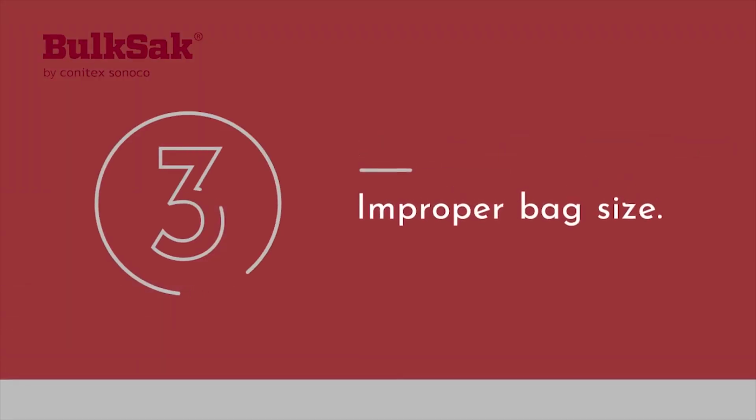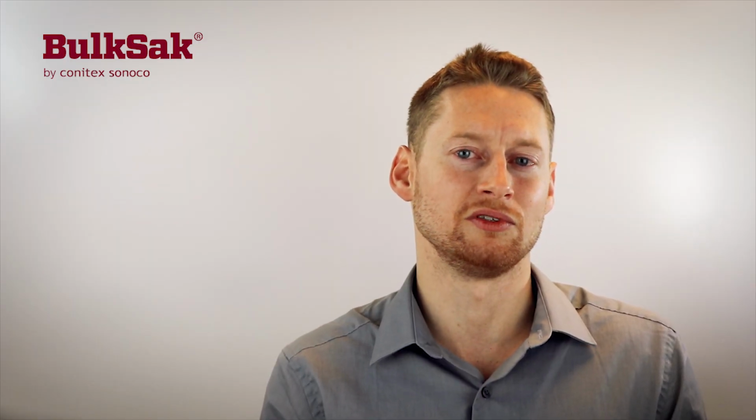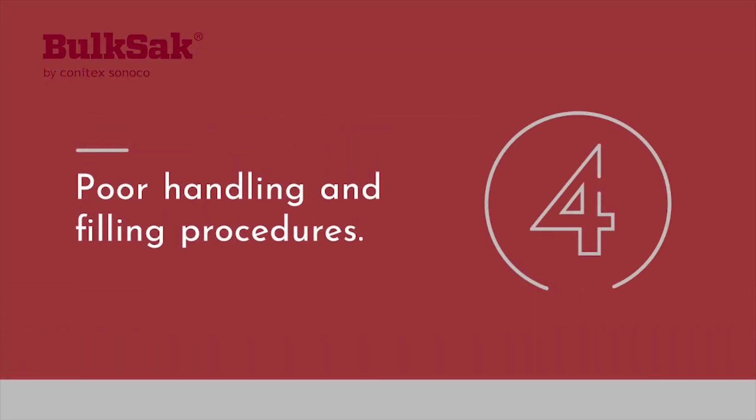Improper bag size is another cause we have seen. Bigger is better in most cases when talking about the top of an FIBC. Sizing a bag and not taking into account the angle of repose usually results in poor product dispersion. Lastly, poor handling and filling procedures can keep even a well-designed bag from being filled properly and efficiently.